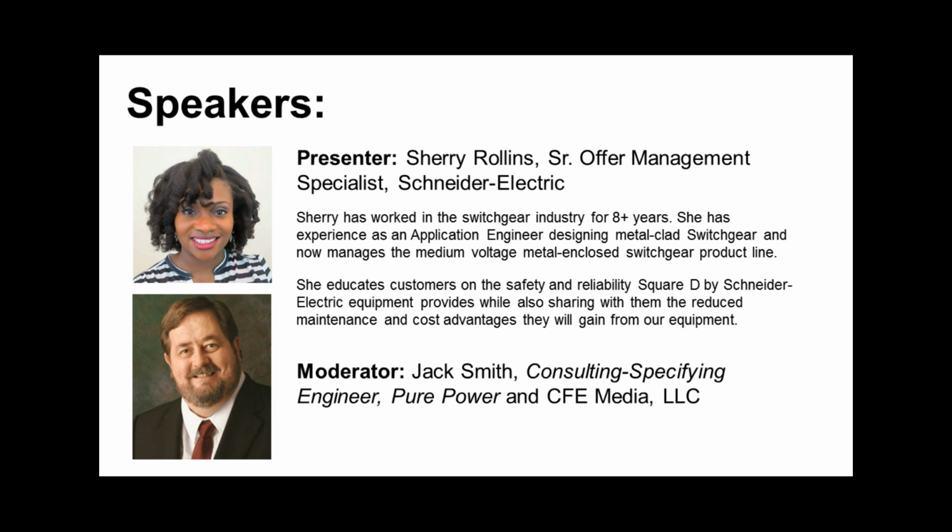And the standard is not a bad standard, but it was designed back in the day, as Sherry talked about in the evolution of switchgear. Older circuit breaker technology, well before vacuum, such as air and oil, required a lot of maintenance. But as we've migrated to vacuum circuit breakers, there's really no service needed on the medium voltage part, the vacuum bottles. Where you see the maintenance needed on switchgear tends to be the trip coils, close coils, and the motor operator. And in fixed-mounted switchgear, all those serviceable items are on the front of the equipment. So really there's no reason with newer technology to remove the vacuum circuit breaker like there used to be.